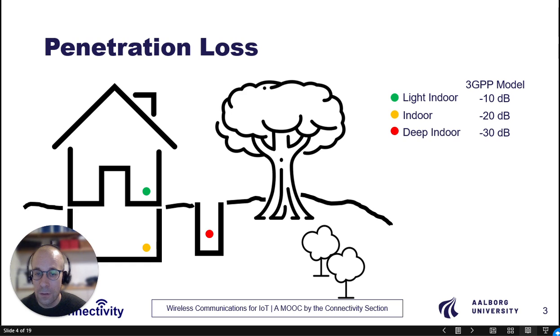And due to the construction of the pit, at least in European standard, it's a concrete pipe where the meter is installed inside the pipe, approximately 1 meter below ground to avoid frost. And this is attenuating the signal quite significantly, especially if the pit is sealed with a cast iron lid.